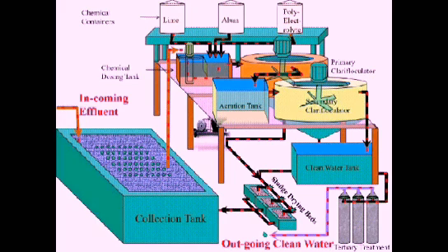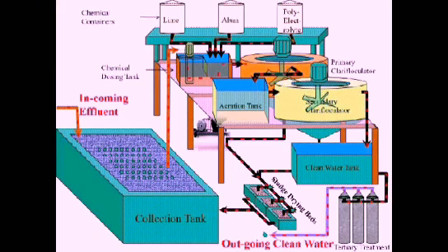Then here we may install an oil skimmer at the entry side of the dosing tank where the oil can be extracted and collected separately outside. In the second half of the dosing tank, where now we have the oil-free effluent, we do the chemical dosing. The chemicals may be stored in containers at a height so that they may be fed by gravity. The details of the chemical treatment would be discussed later.